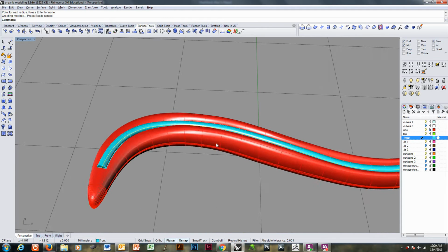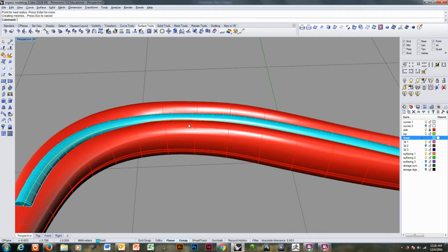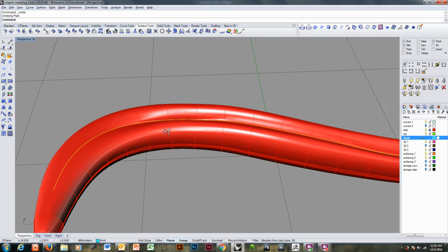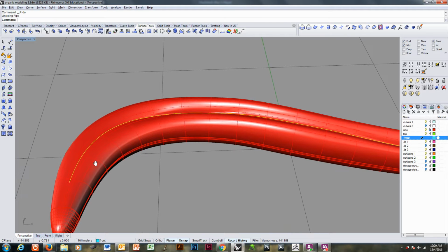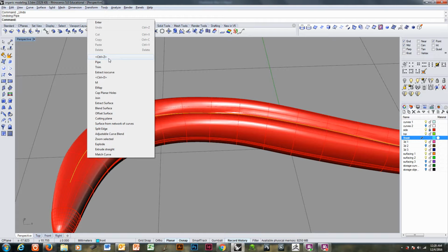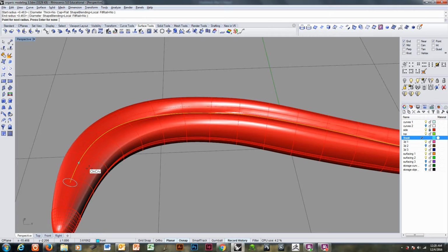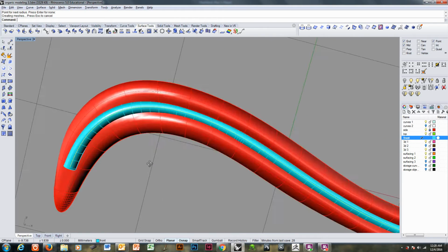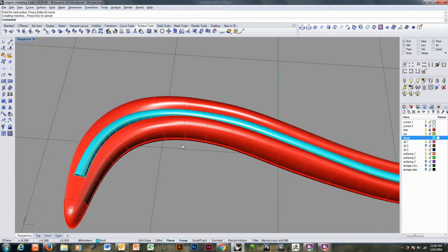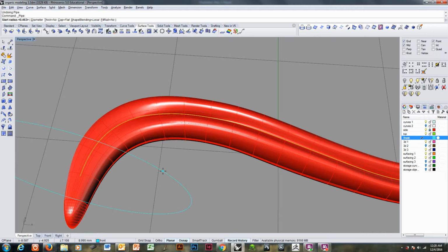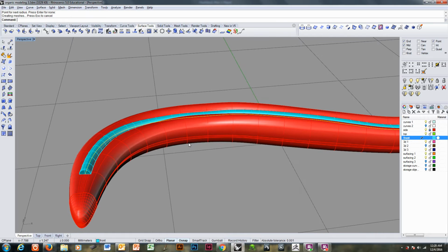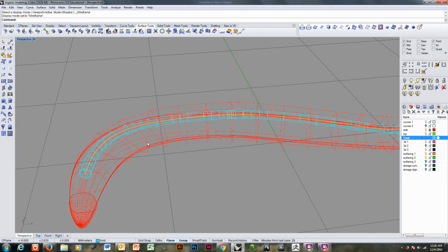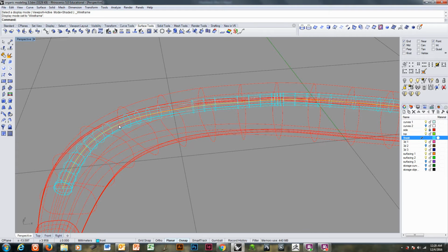Now this pipe is being consumed down inside of my piece, which I don't really love. It's a little bit of a bother. So I'm going to record history and redo that pipe. Because I do think that's a reasonably nice thickness, maybe a little less. That's 0.46. I'll make it 0.4. I'm going to turn on control points for the center curve.